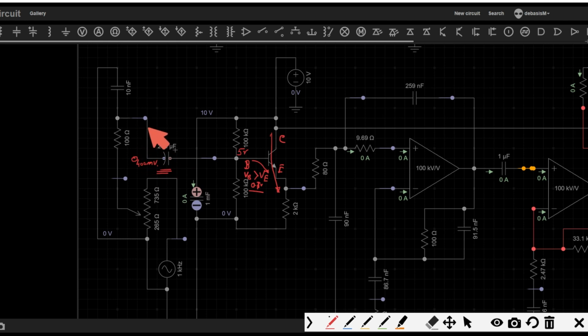So when, let's say, this voltage is 0 and this is 5 volt, there is a delta of 5 volt between the plates of this polarized capacitor. Now when some voltage comes in at this terminal, like 400 millivolt, the capacitor tries to push this voltage up so that the delta V, that is 5 volt, remains. So when this voltage is 400 millivolt, eventually this voltage will try to become like 5.4 volt. That way this transistor detects the audio voltage signal.